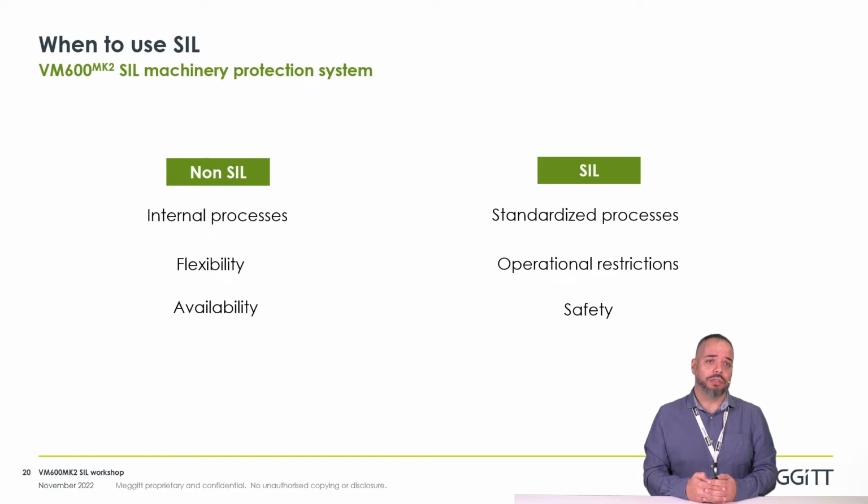Whenever there is an issue with the equipment potentially affecting the safety function, the system shall fall into a safe state, typically meaning that the trip of the machine will occur. Note that you can increase the availability of a safety system by increasing the number of equipment in parallel, for example using a 2 out of 3 architecture.